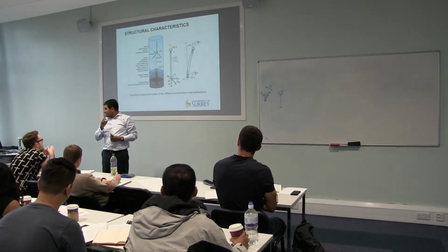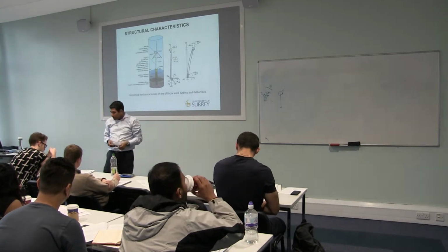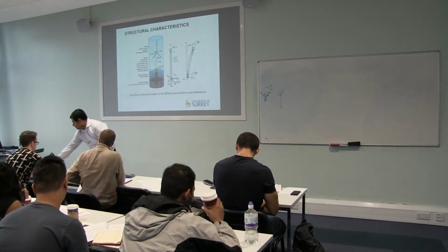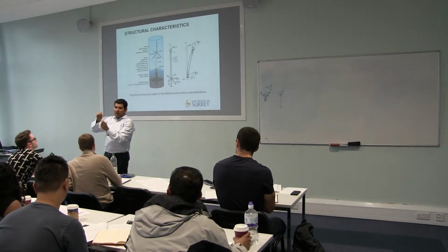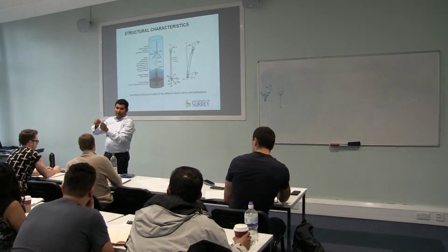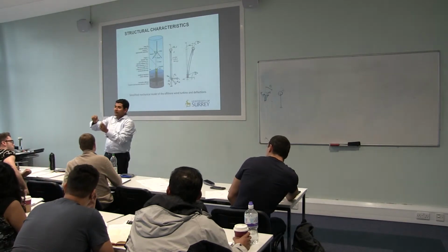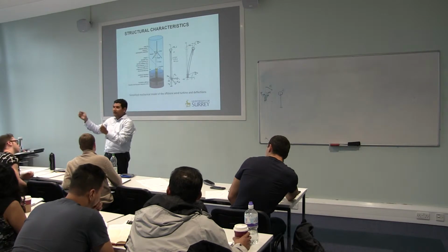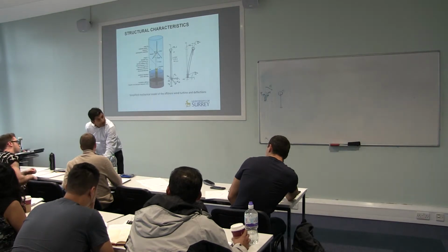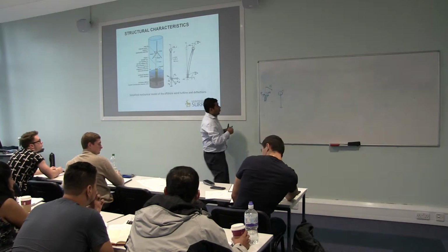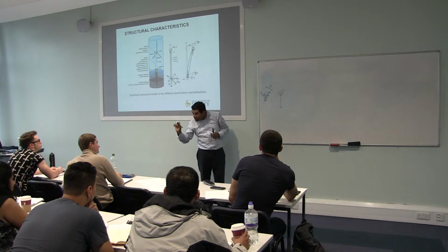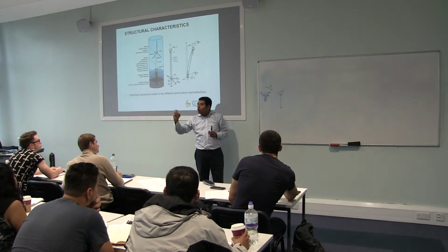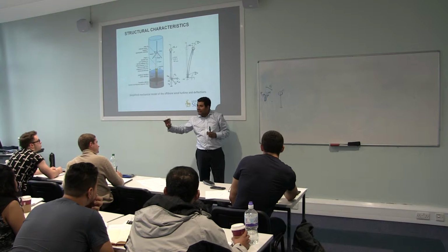Frequency basically means, if I take this structure like that and I give a small tap and then see how it decays. Once I take the load off, it will start to vibrate at its own frequency, and that frequency is the natural frequency. Once I give a small perturbation or a small disturbance, that is a load off, it would decay naturally.